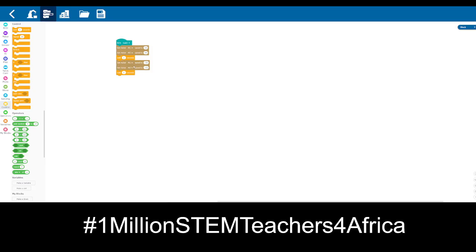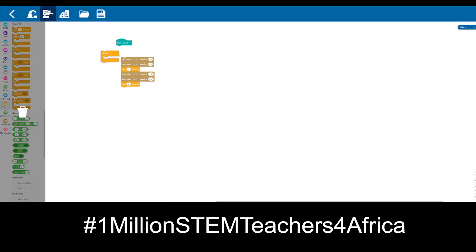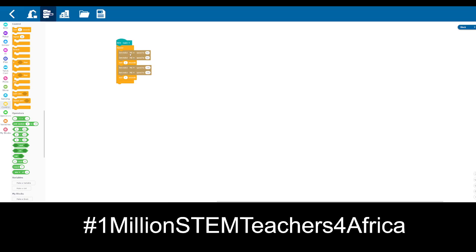So now, for us to ensure that once this robot is here, it goes back again, we have to put this in a loop. This is open. We have no feedback. We don't know if the robot has reached there or not. So we have to put a loop there, forever. This robot will move forward, speed of 50, motor 1, motor 2, and that should happen in 1 second. And then the other second, it should be moving reverse.